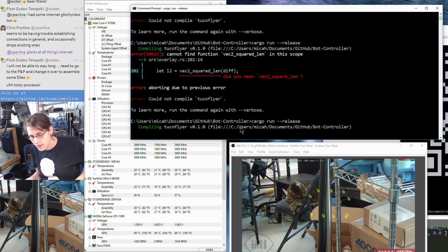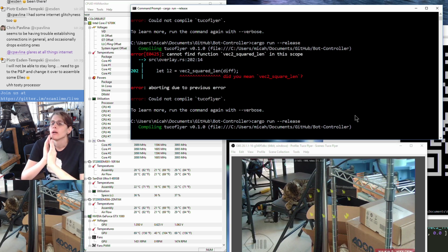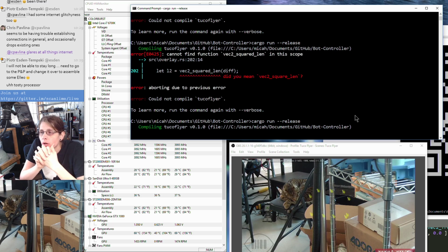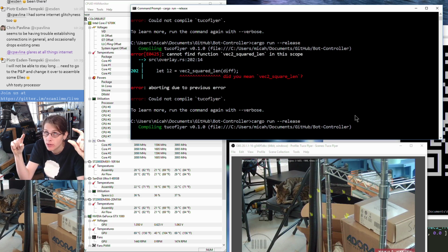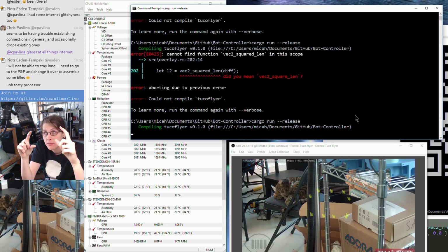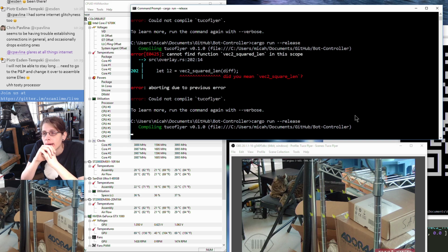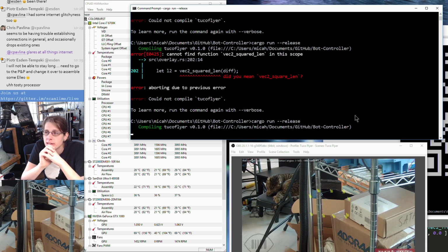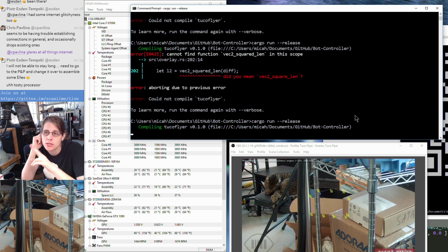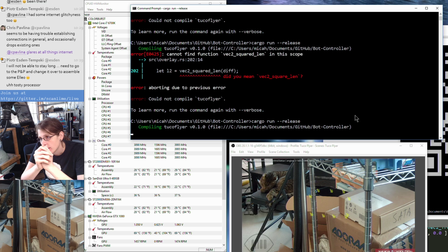All right, so what's next? Oh, so I was talking about how the new gain controller will work a little bit, where right now it has these rectangles where when the computer vision rectangle overlaps a gain rectangle, it applies a force to the gimbal. And I want to replace that with something one-dimensional so that the size of the rectangle doesn't matter so much as the amount to which it's exceeding the limit that I set. And I think that'll be good.